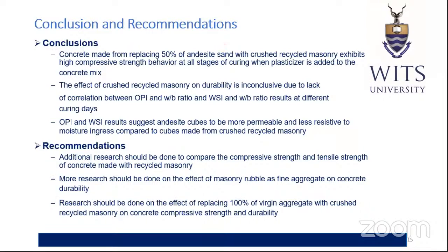Based on our experimental results and analysis, we can conclude that concrete made from replacing 50% of andesite sand with crushed recycled masonry exhibits a high compressive strength behavior at all stages of curing when plasticizer is added to the concrete mix.